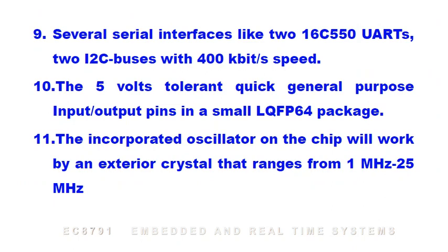Several serial interfaces like two 16C550 universal asynchronous receiver transmitters, and two I2C buses with 400 kilobits per second speed. There are 5-volt tolerant fast general purpose input or output pins in the small LQFP64 package, 64-pin package.